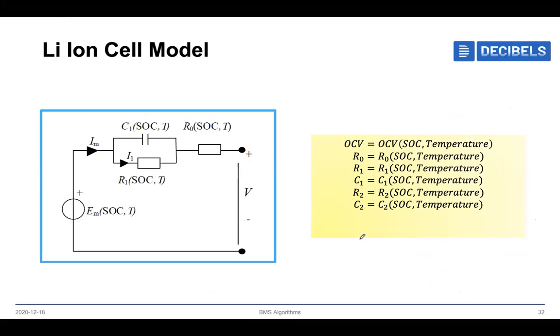But for each and every functionality, I spoke about the lithium ion cell model, right? And I also told you about the equivalent circuit model of lithium ion. So this is how exactly it will look. This is called a Thevenin model. All the physics-based models are converted into equivalent circuit modeling. In equivalent circuit modeling, we have four different types: one is the ring model, Thevenin model, dual polarization model, or neural network model. So one of them is this one, which is the Thevenin model.